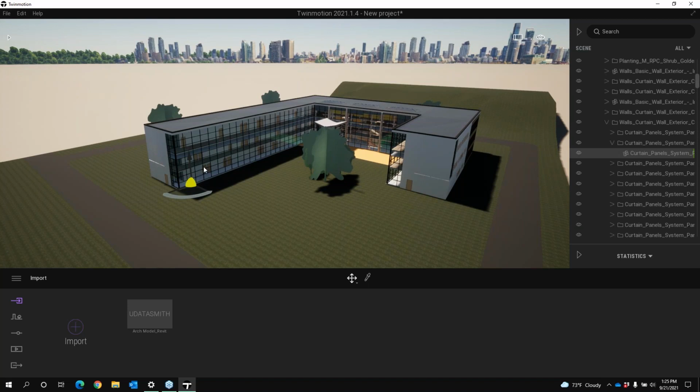When it comes into Twinmotion, they're individual elements. So it's very difficult to create a selection specifically of maybe a certain row of the glazing and mullions on level 1, or certain elements within the model. You really have to become an expert at sifting through the scene graph and selecting them individually, or holding the control key down and selecting multiple elements.